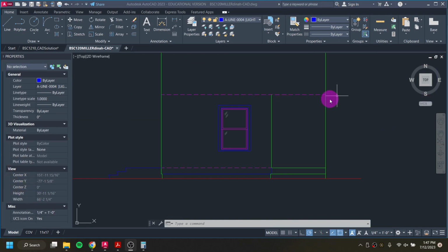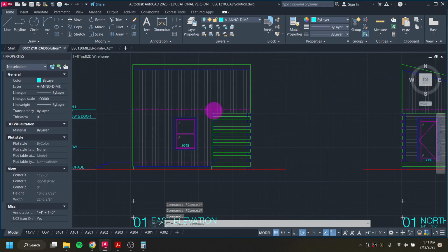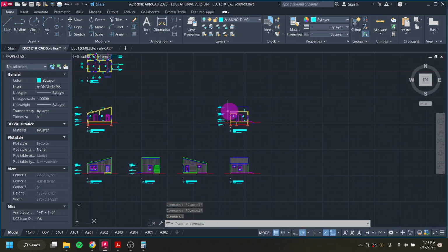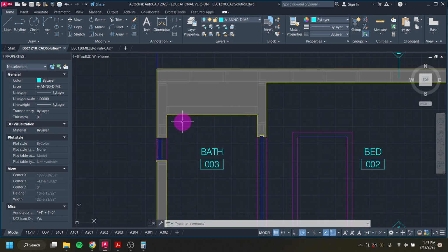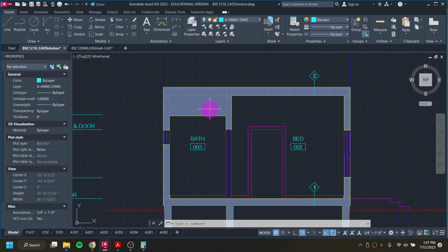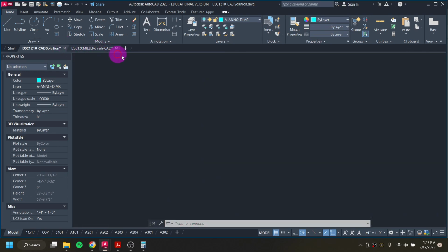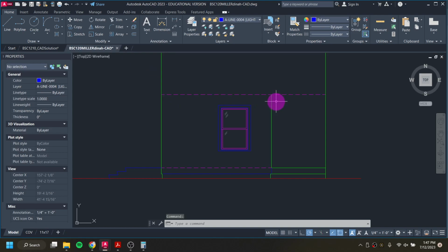Next, before we put in things or start relating to our privacy wall, we're just going to have to put in that little bit of ceiling height that sits on the bathroom. So the ceiling, we can see that ceiling height a little bit more in this section view. Again, this one's optional. So it's a 1/2 inch piece of gypsum wallboard, and then it's our 2x6. The way we detail how far down that ceiling is going to go is it's 7.5 down.